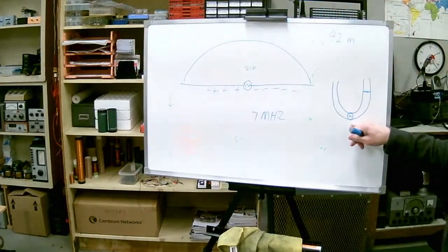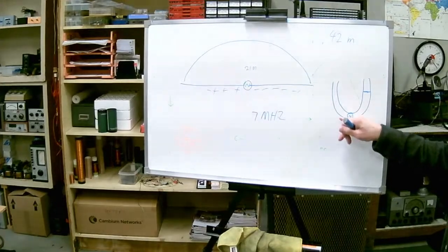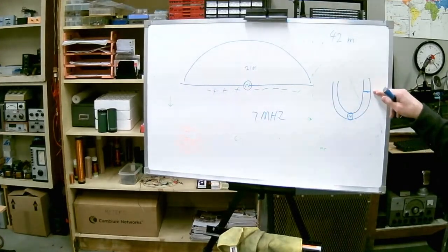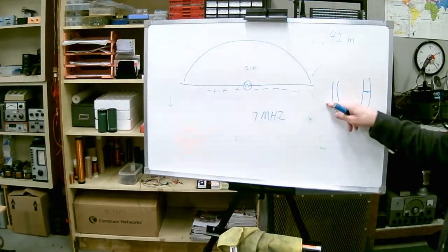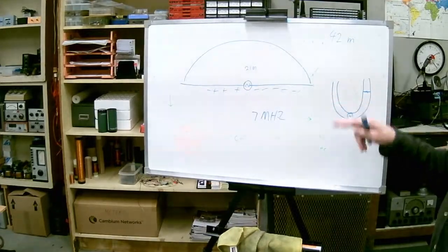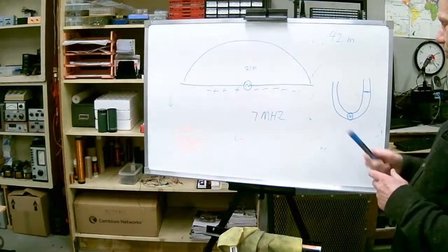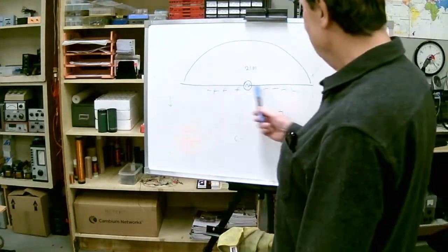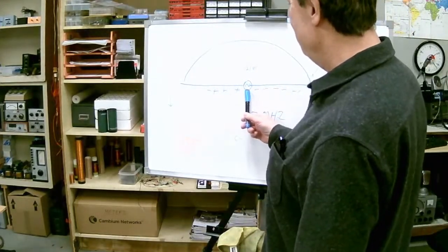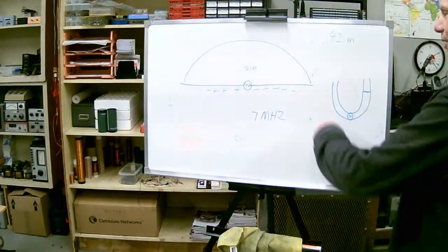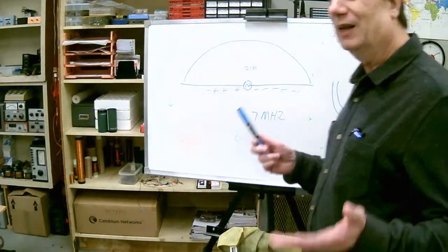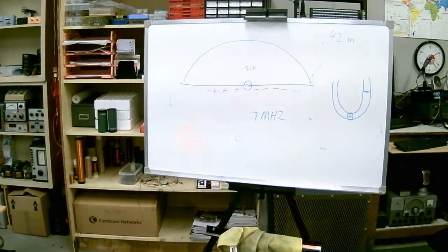At the midpoint, we have the most water flow here. Everything from this point on has to go through that point. But the farther away you get from the pump, the less has to travel through that point. So every electron we slosh through here has to pass through the midpoint, but as we get closer to the end, we have progressively less current flowing at this point.